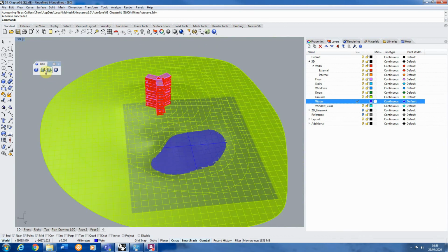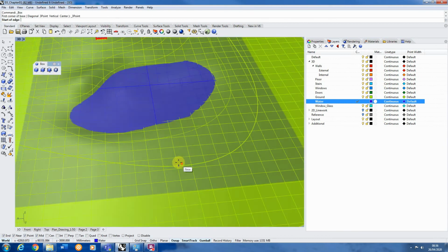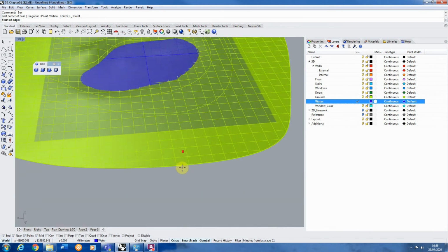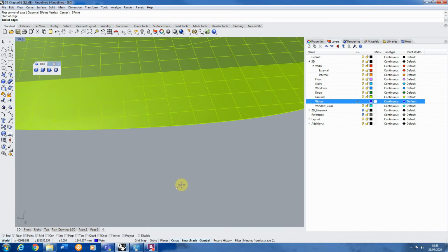Now it's really important whenever you're doing perspective views that you do them from a person's eye level, and the reason for this is that any views we see of buildings in reality we're seeing from our own eyes, and if you don't set a camera in a 3D space at eye level it can make all your doors, windows, all the scale of your building look slightly incorrect. So it's important that you set up all your camera views from eye level to make sure that there's no discrepancy and that you can clearly see the scale of the building there.